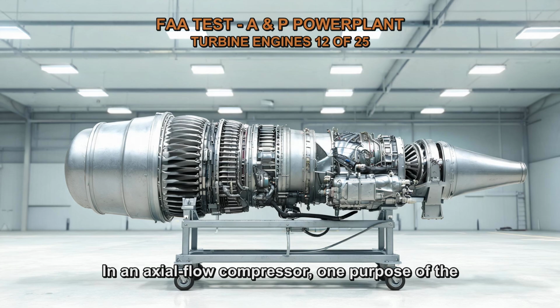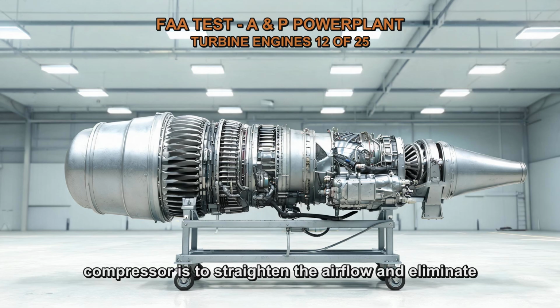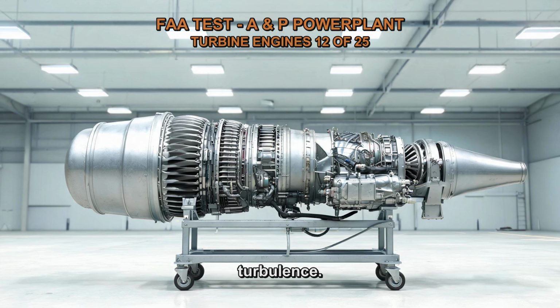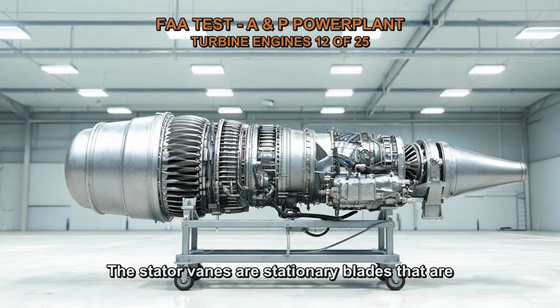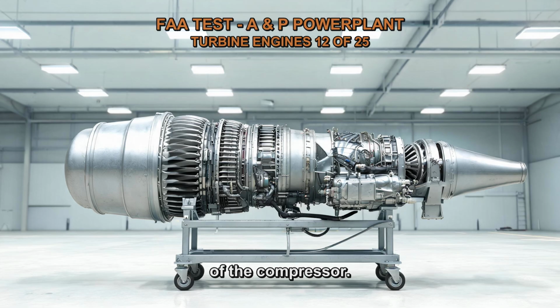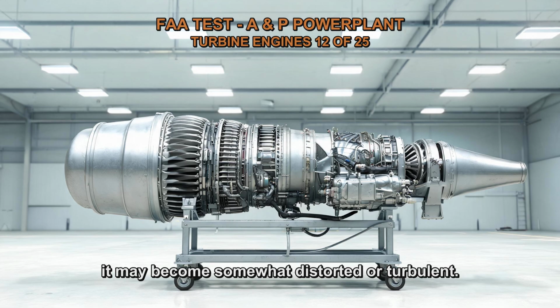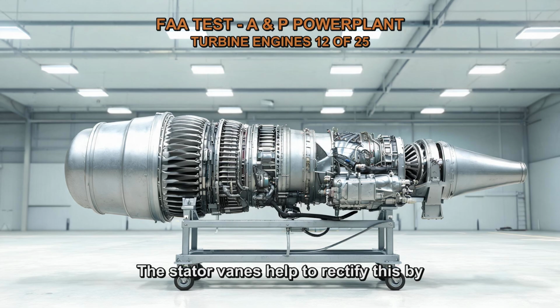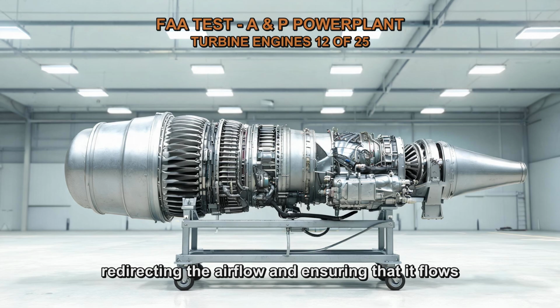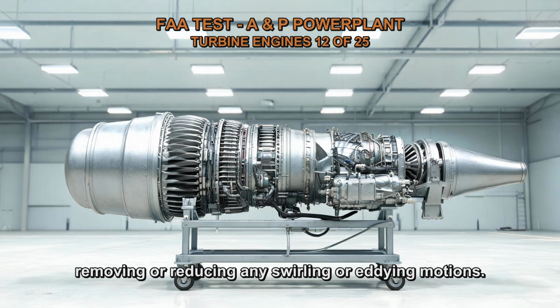In an axial flow compressor, one purpose of the stator vanes at the discharge end of the compressor is to straighten the airflow and eliminate turbulence. The stator vanes are stationary blades that are positioned between the rotating blades or rotor stages of the compressor. As the air passes through the rotating blades, it may become somewhat distorted or turbulent. The stator vanes help to rectify this by redirecting the airflow and ensuring that it flows in a more uniform and straight path. The stator vanes straighten out the airflow by removing or reducing any swirling or eddying motions.